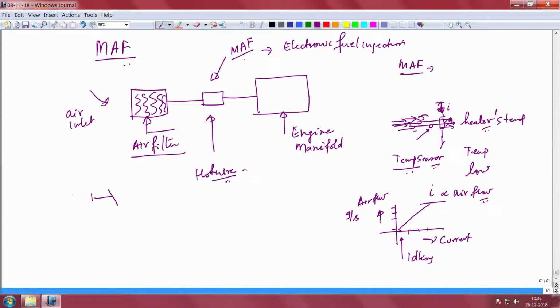Remember, I had connected it to a potentiometer, right. So, this is the accelerator pedal. If you press on the accelerator pedal with your leg, the throttle will open and that will allow more airflow through the hot wire. It will allow more flow through the hot wire, and that will be proportional to that airflow you want to measure.